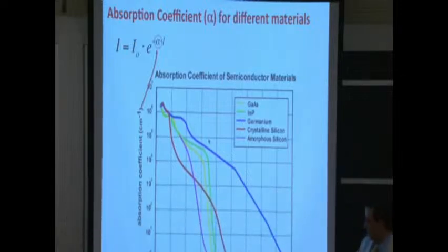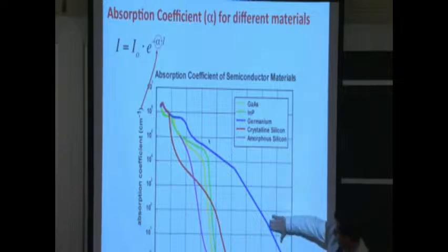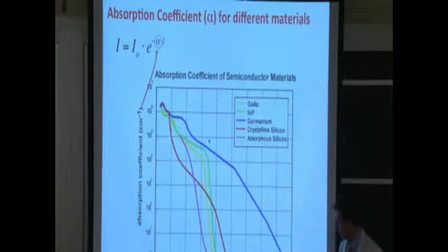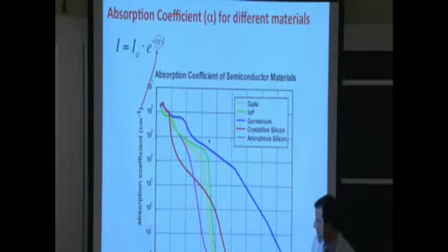That's important because we'll be referring to them very naturally as a photon either having a certain wavelength or a certain energy. And you notice that there are certain turn-on energies, right? So energy is increasing in that direction there. As we go from infrared to ultraviolet, the energy of the incoming light is increasing. And if the energy is too low, the semiconductor crystal just won't absorb. The absorbance is 0 or very, very small.